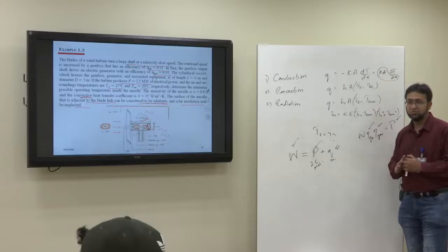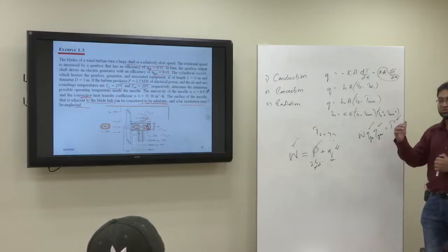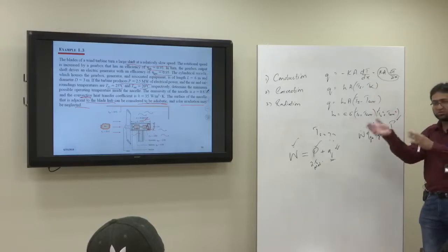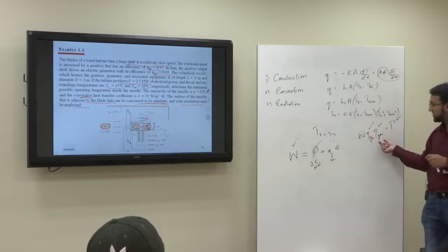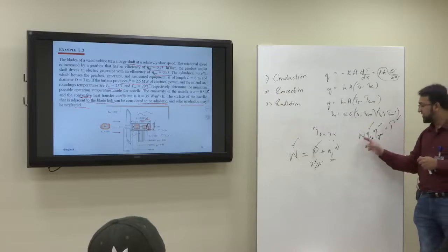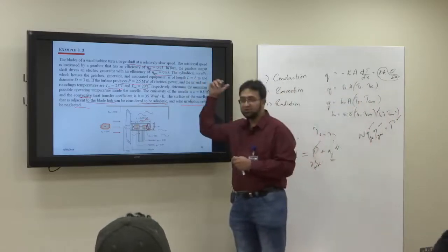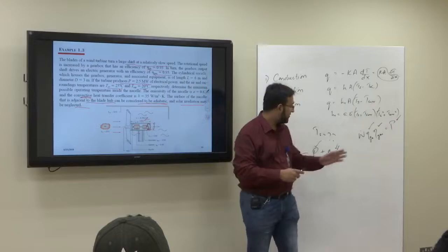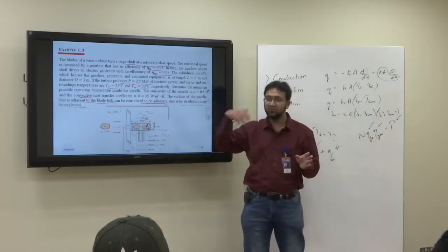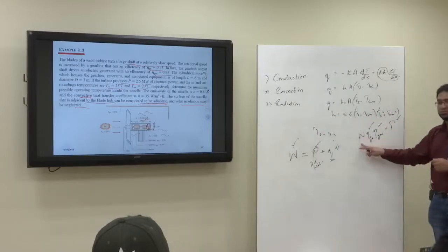Again, this is how you find W. How did I find the W? Look, this is the input power. Input energy multiplied by the efficiency of the gearbox will give the energy transferred to the generator. Multiply by the generator efficiency will give the output power. Whatever, let's say 100 was the energy incoming, so 100 multiplied by this, 93 will be going to the generator. Then 95% of 93 will be converted into power, right? So P we have. But we have P, we don't have W dot.